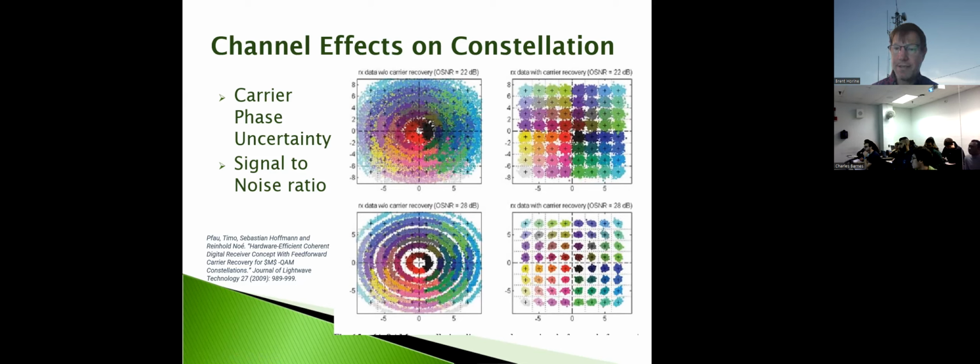If you're in a mobile communications situation, the path length, measured in number of wavelengths, matters, because a wavelength of propagation means that your signal is going to cycle through 0 to 360 degrees, or 2 pi radians, of phase shift throughout a wavelength.